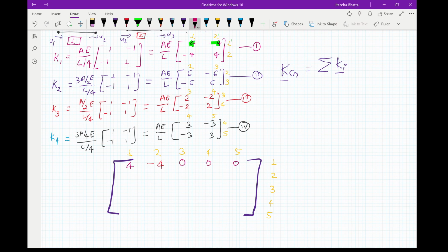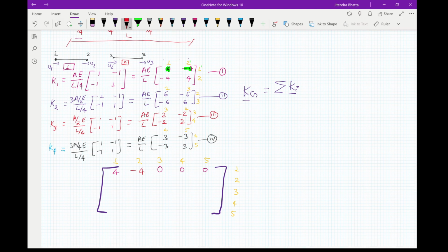This just means that when you are solving at each element level like this, let's say this is 1, 2, 3, 4 and 5, you're actually fixing all these boundary conditions. Therefore, the displacement you give here will only have a reaction force here, and this force won't transfer to these nodes. Therefore, you'll have 0 values there.